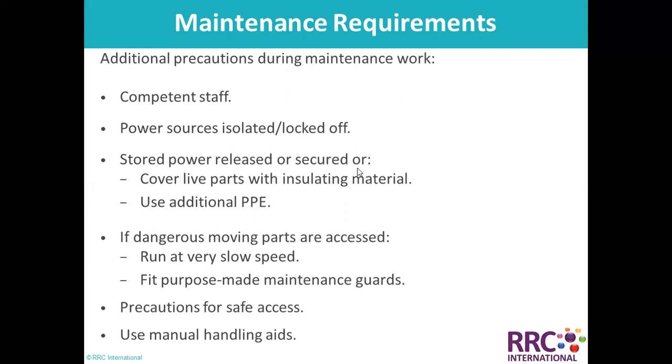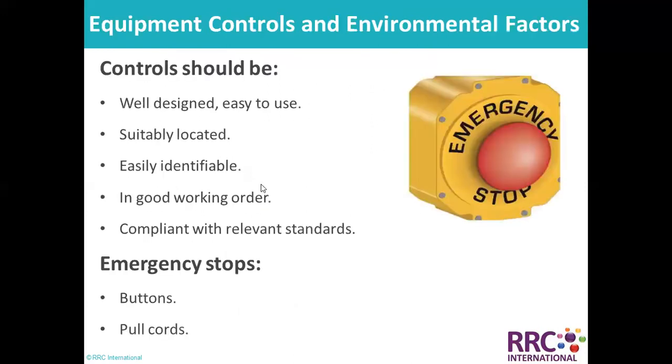Store power leads securely or cover live parts with insulating material. Use additional PPE. If it's dangerous for moving parts or access, run at very low speed and fit purpose-made maintenance guards also. Take precautions for safe access and use manual handling aids as well. So these are some of the requirements for maintenance.